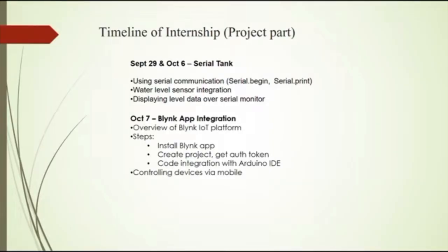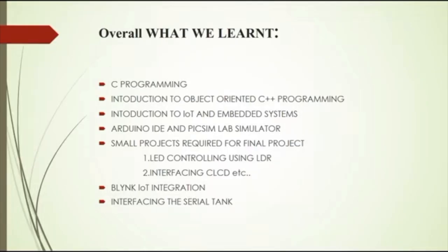Then we learned about Blynk app integration. How to integrate the Blynk app with this project: first we have to install the app, then create a project, then generate the authentication token, then use this token in code integration with the Arduino, then control devices via mobile.